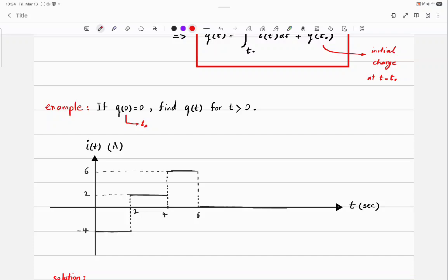Negative 4 amps times 10 volts. Anyone having a problem with what he said? What is the first negative sign for? Because the current is entering from the negative terminal, so if you multiply those two numbers, it will give you the supply power. So you need a negative sign to change it to absorb.